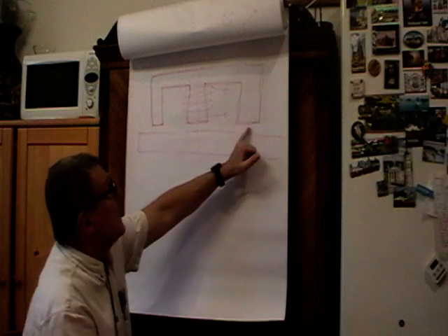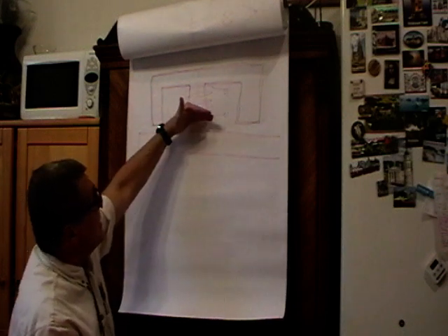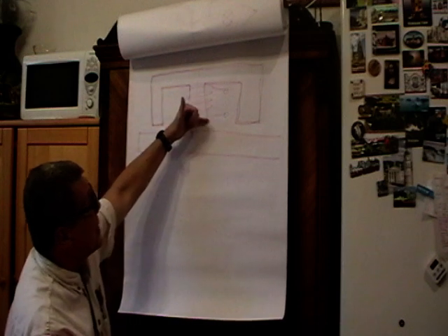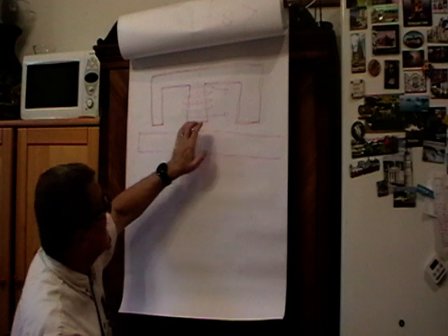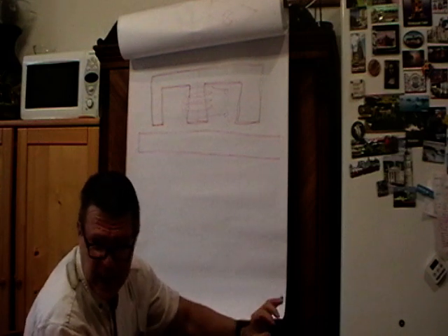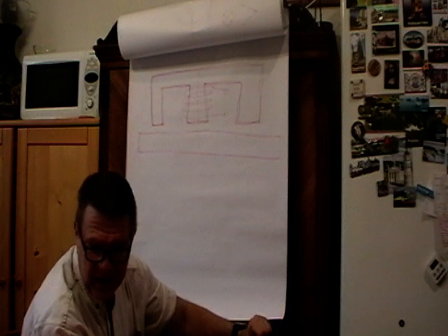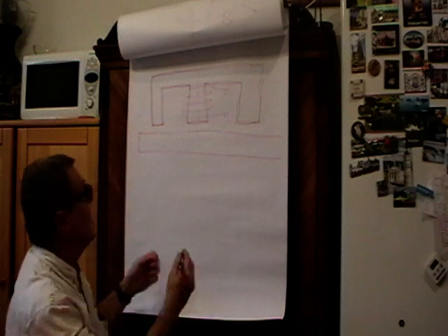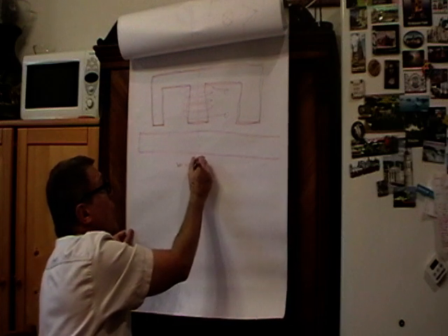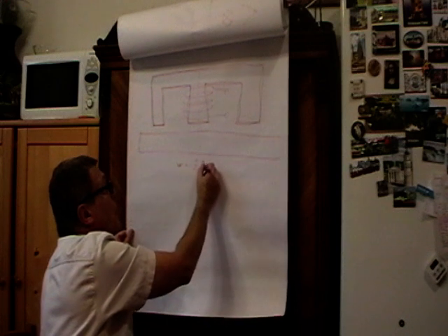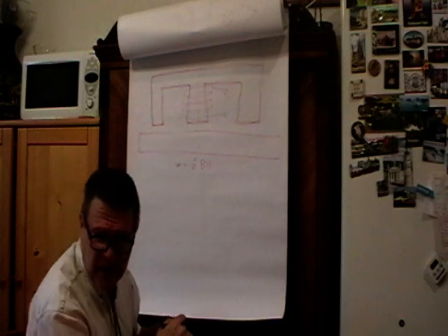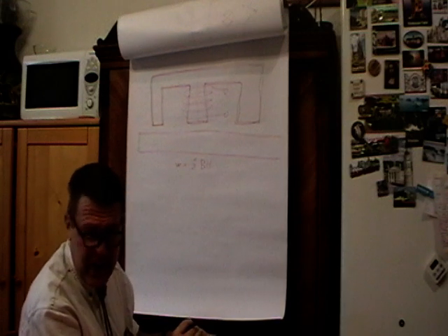So what is the density of energy? As we have the double flux here and the double surface or cross section, the energy density in all three air gaps would be more or less identical, and it would be, again, W is 1/2 of BH. Now we can omit vectors since everything is collinear.